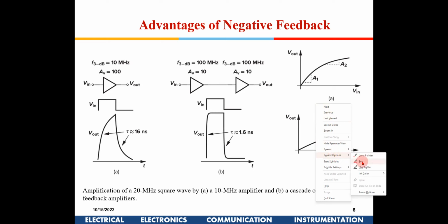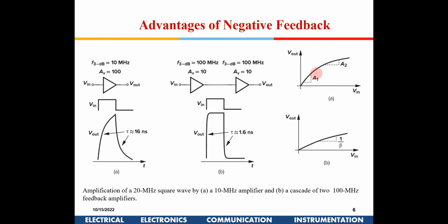I understand your point. Now, this is a Vn. In the first case and in the second case, both have to cater for this input range. Now, for this amplifier, as long as the output is this much, it is kind of linear. In the first case, I am restricting my gain till here, so the signal will be like this. It will be linear.